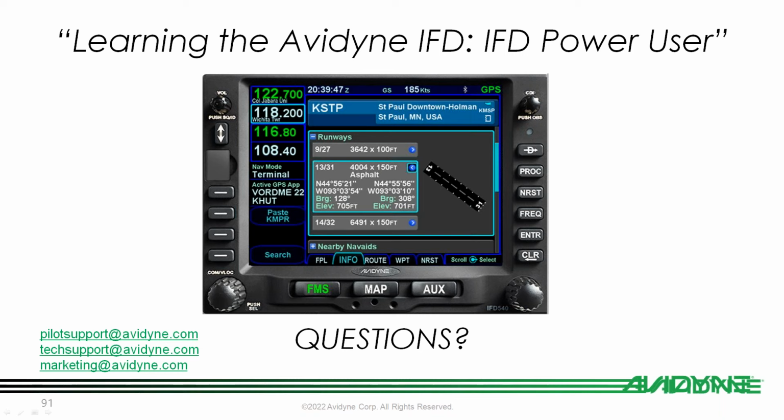Thank you. Hey Mike, I had one real quick. It's about the top of descent function. When you're going to an airport, I know this is normally en route, but is it possible to do top of descent to an airport? And if so, could it be at pattern altitude or to the runway elevation? So there is a begin descent cast message that will show up, but your downpath waypoint has to have an altitude constraint.